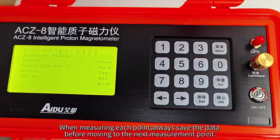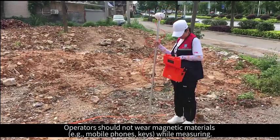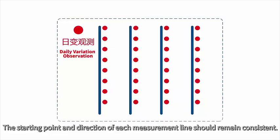Precautions: when measuring each point, always save the data before moving to the next measurement point. At each measurement point, the direction of the sensor should remain unchanged. Operators should not wear magnetic materials, for example, mobile phones and keys, while measuring. The starting point and direction of each measurement line should remain consistent.